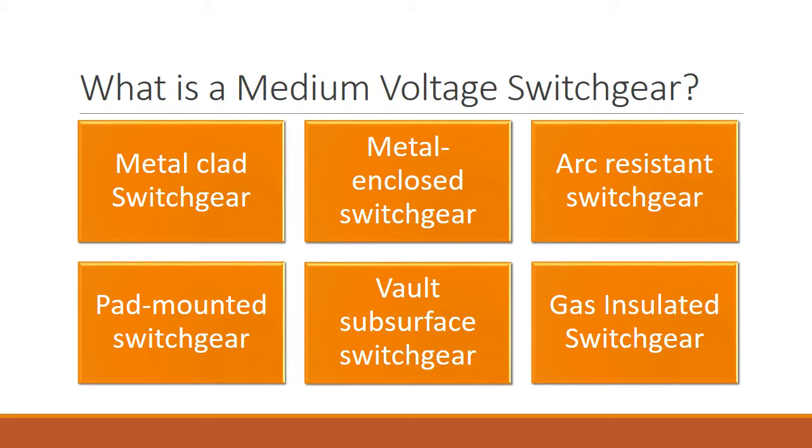Now, switchgear may be found in a variety of places, including electric utility transmission and distribution systems, as well as medium to large commercial and industrial buildings. Now, IEEE defines the electrical switchgear standards in North America, and the IEC would be the one that defines those in Europe and other areas of the world. Now, the medium voltage switchgears that we focus on in this mini course are switchgears with voltage levels of 2.4 kV to 69 kV, kV meaning kilovolts.